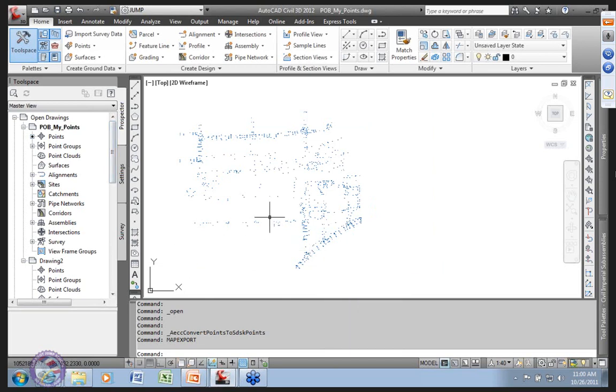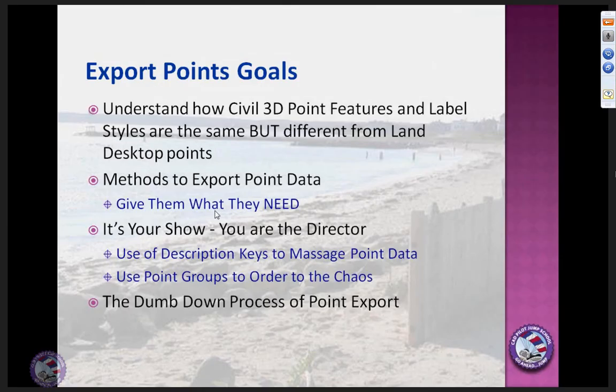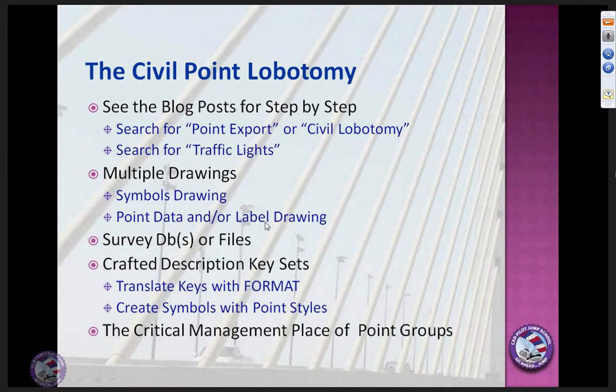Save as DGN will give you a very nice picture that shows up in DGN. Once again, they'll all be wrappered, sort of. They'll all be in cells, right, same sort of effect that we saw in AutoCAD happens over in MicroStation, and they may not like that almost non-editable result, but that may be all they need to print on top of what you deliver to them, which, once again, returning to our slideshow, give them what they need.